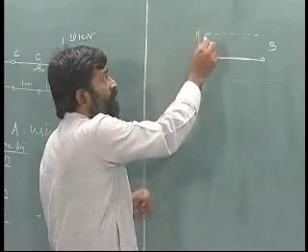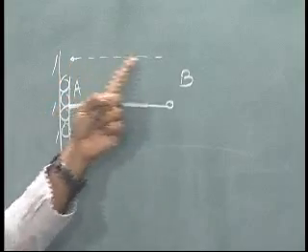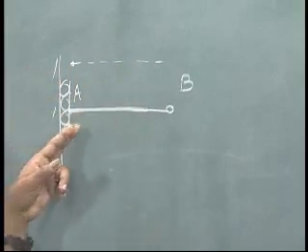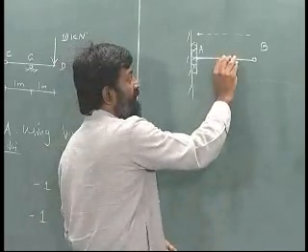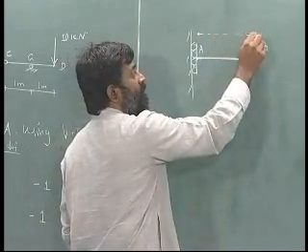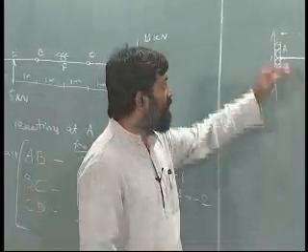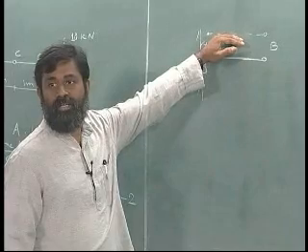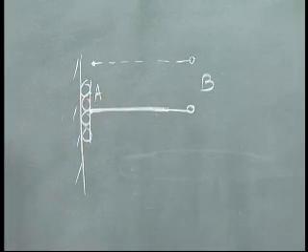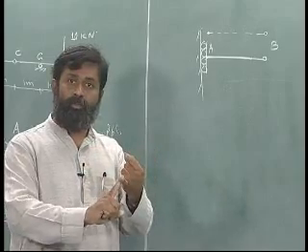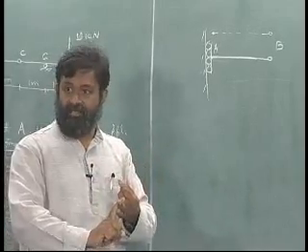So when I move this up, this point cannot rotate. If one point of the rigid body cannot rotate, none of the points of this AB can rotate, and therefore it has to only go up like this till point B. That is the only possibility. Okay, and therefore we did this way, consistent with those two assumptions, with the support conditions and the rigid body notion.